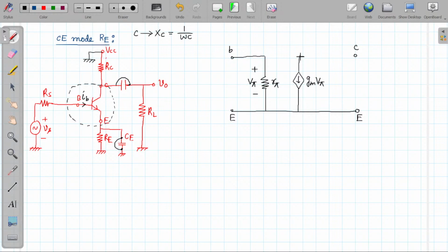And there will be an admittance value, and the admittance value will be R pi. So this is R0. Now, in the circuit, you can see that this is an NPN transistor. So IE current will be in the outward direction, and IC will be in the incoming direction. So that means here we can replace that there is the base current and this is the collector current. And all are AC currents because we are doing the AC analysis.